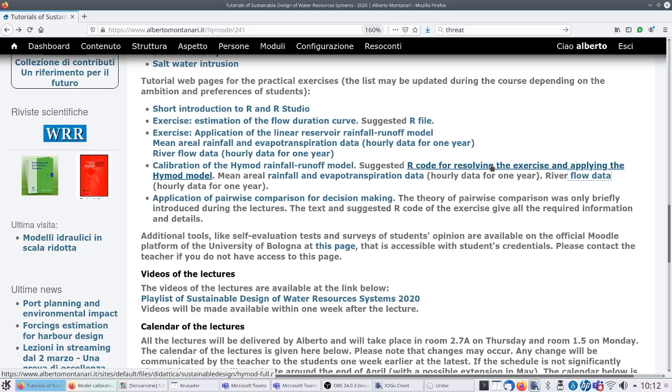You have to gain an expectation, like you make a computation of the thickness of a dam, and you gain an expectation, like it should be something around 10 meters rather than 100 meters. You need to know the orders of magnitude, and you need to know the theory behind it, in order to get a preliminary idea.